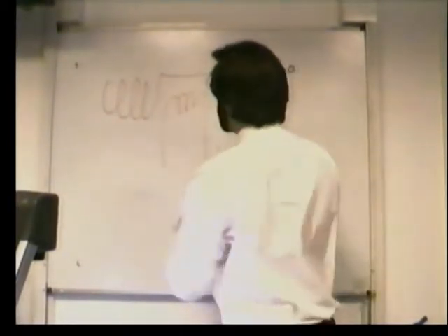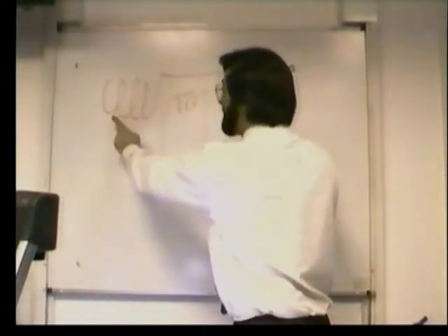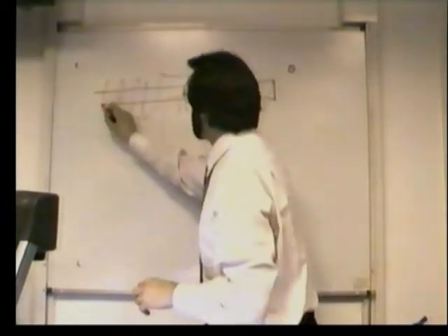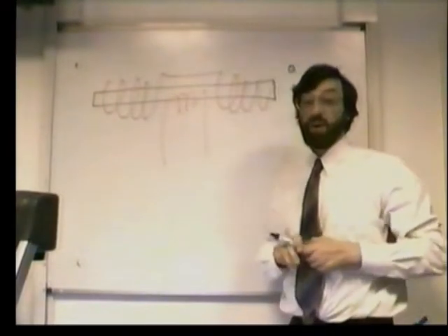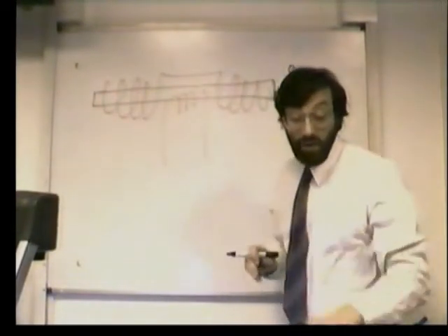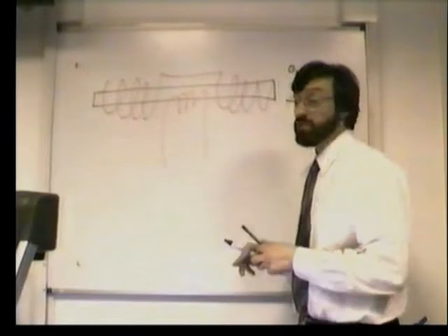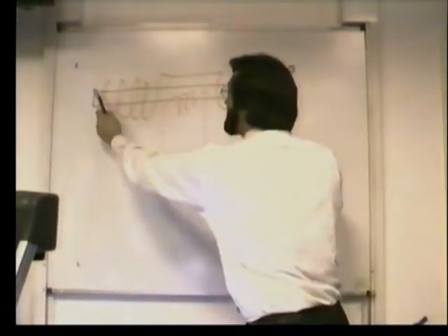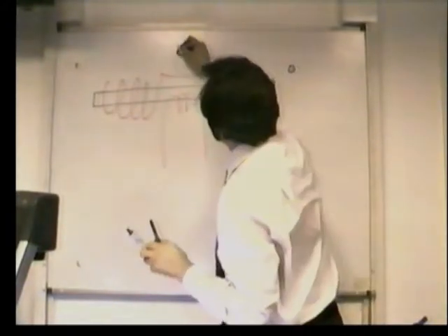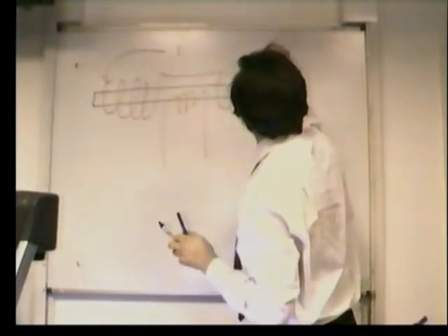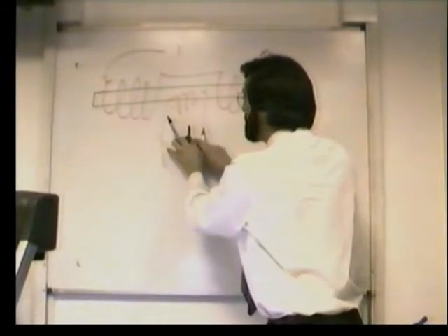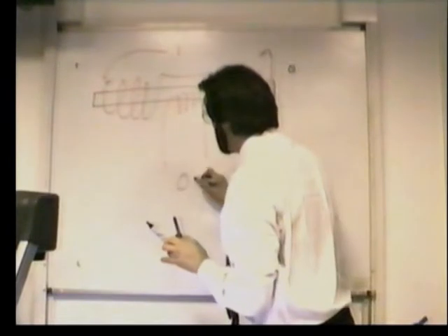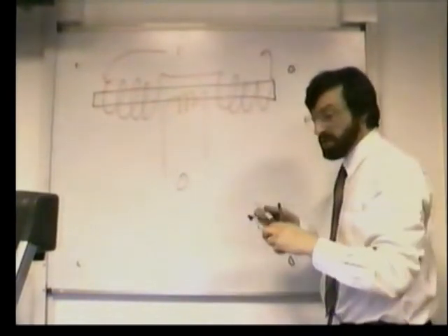If we have a pair of coils balanced on either side, a primary with a secondary, and we put in the middle of it a ferrite core, a bit of iron or some form of ferrous material, then physics tells us that when that is dead central, when a current is flowing through the primary, we will get induced into the secondary equal and opposite currents, and we will get zero out in terms of current. But